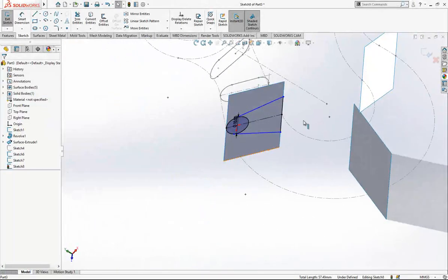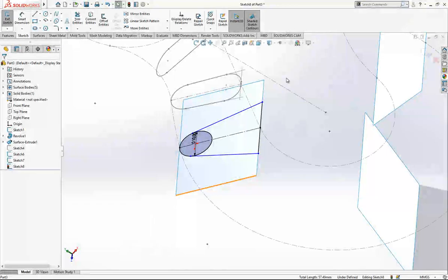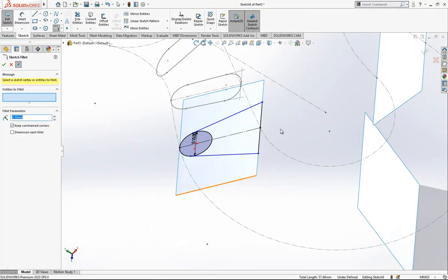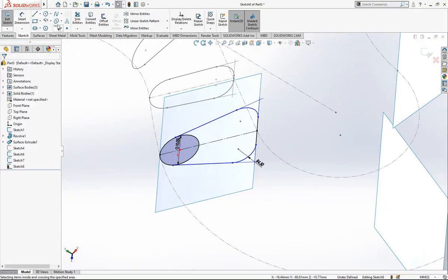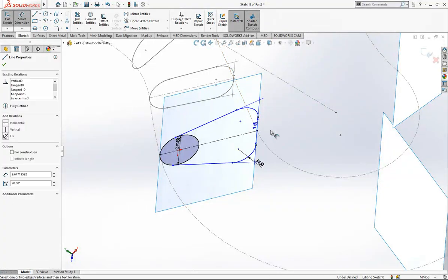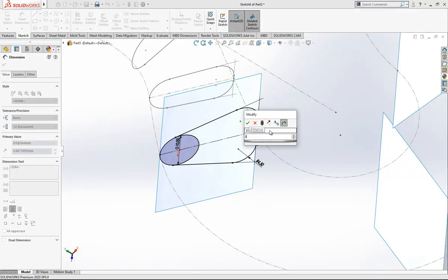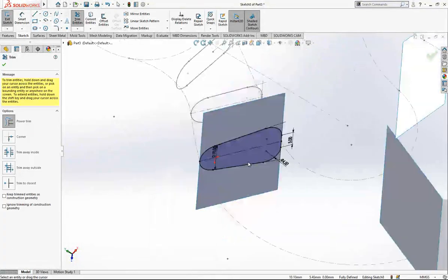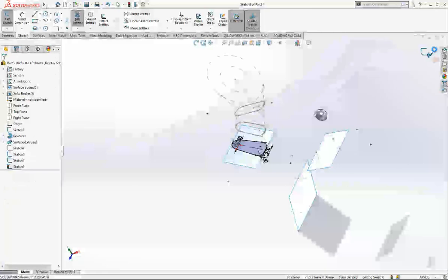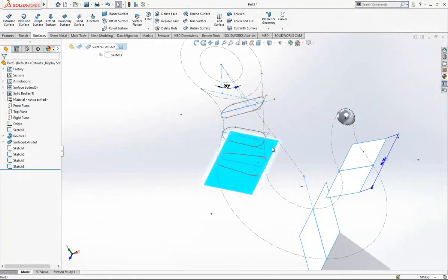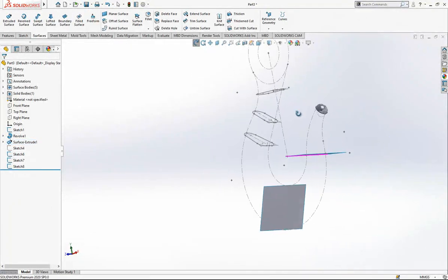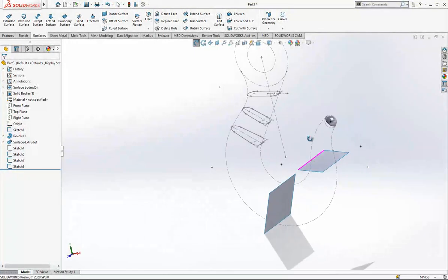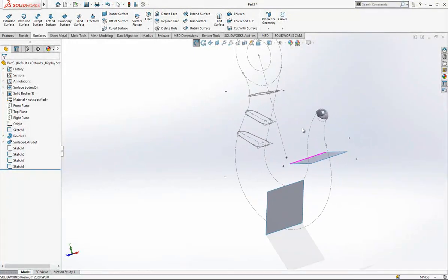I pick two objects while control is pressed, and then I'm saying this will be our mirror. And now we are going to give again 2 times 4.5 radius on the edges. It is looking good, and this line will be 5 millimeter. From narrow to wider, we are passing through sections. We are going to make 2 more sections, and then everything will be fine.